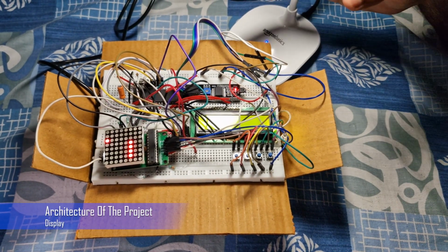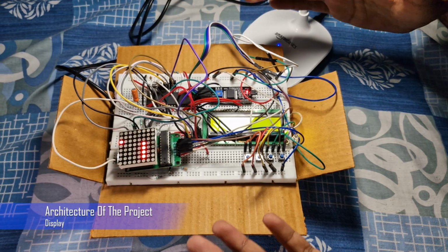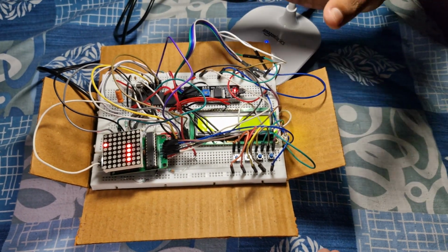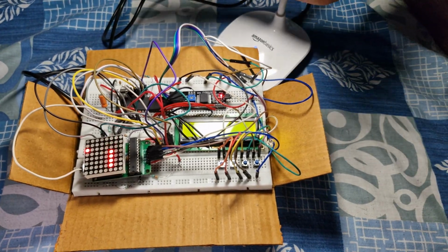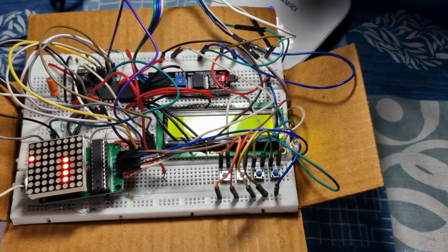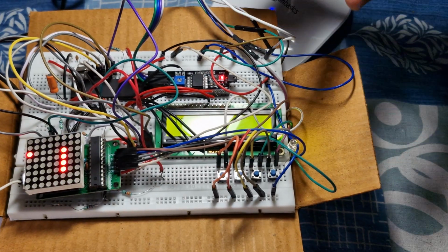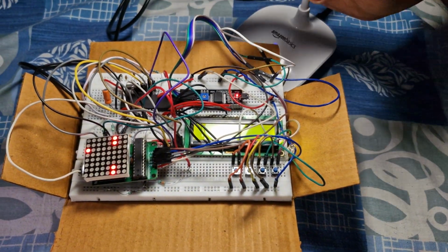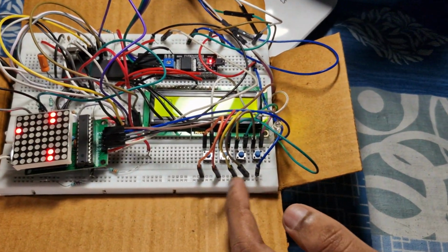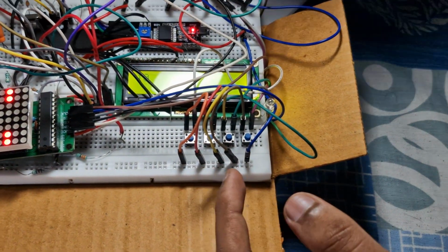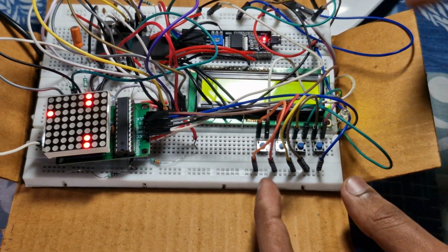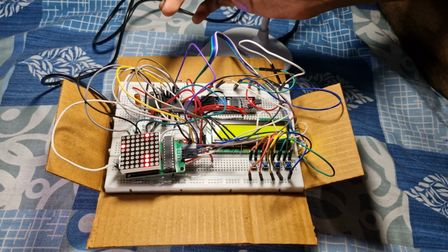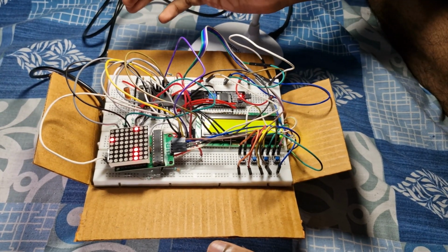Let's have a look at the display for the 8051 Snake game implementation. We use a typical LCD program where port 1 is used for the controls and port 0 is used for the data pins. The remaining pins of port 1 are used for the buttons that control the snake in the game. We connect ports 2 and 3, set as output ports, to the dot matrix display.